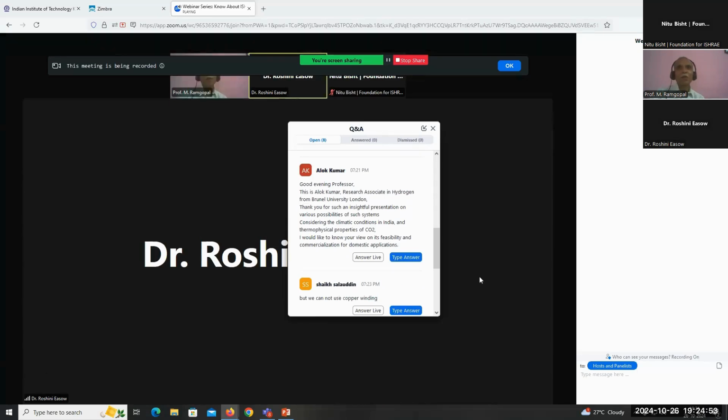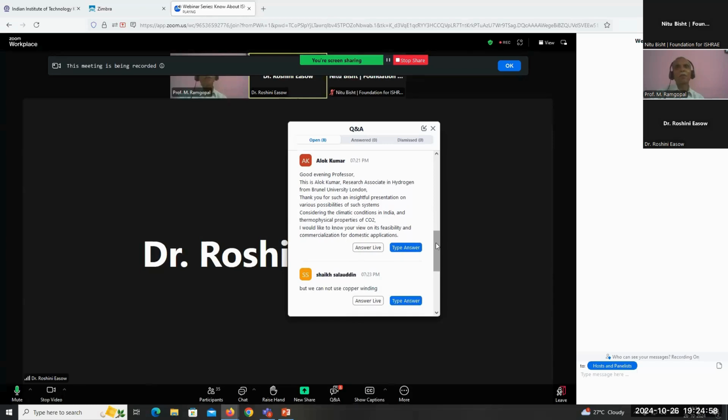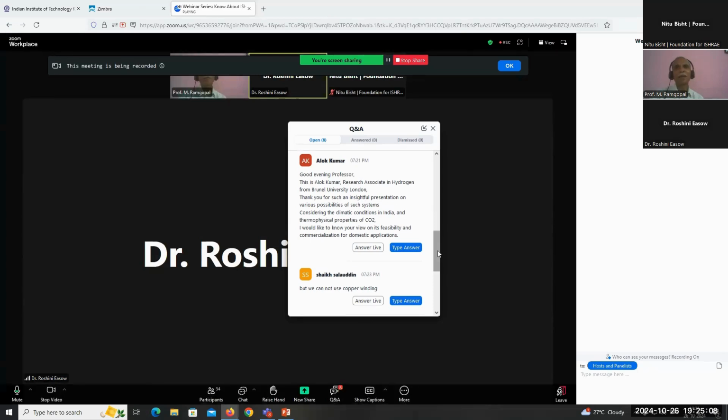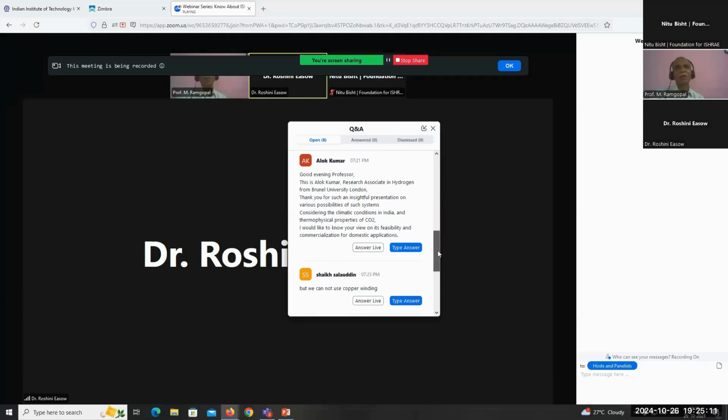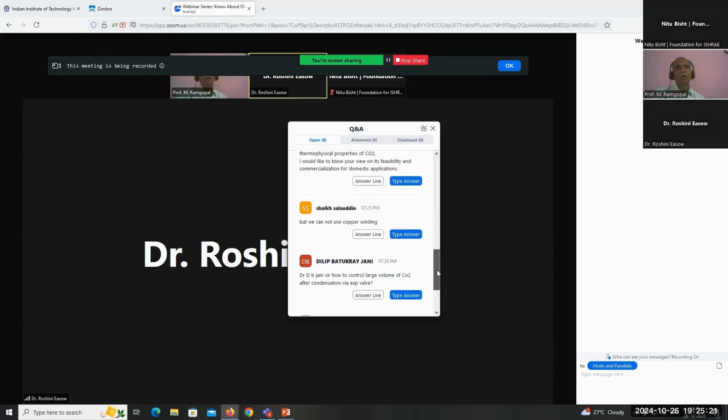I would like to know your view of its feasibility and commercialization. See, the only effect of climatic condition is if the outside is hot, then when the system is off, the operating pressures can be high. Only that has to be taken care of through proper system design, internal volume, and all. Otherwise, I don't see any big problem. So we have to design it for higher pressure. I think it is feasible. Of course, copper cannot be used with any ammonia system because we have to go for MS steel piping, just like a conventional system.